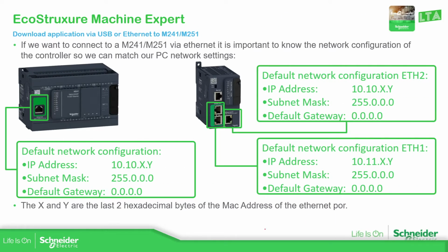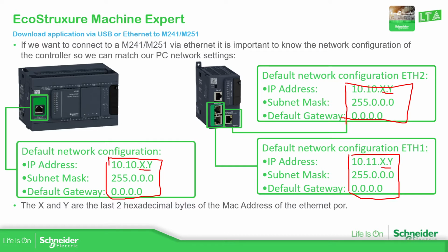If we go to the full view, we just need to make sure of the default IP address of the default network for this controller, so we can match the network configuration in your laptop. The XY that you have seen over here belong to the last 4 digits that you have in your MAC address. Let me just show you.